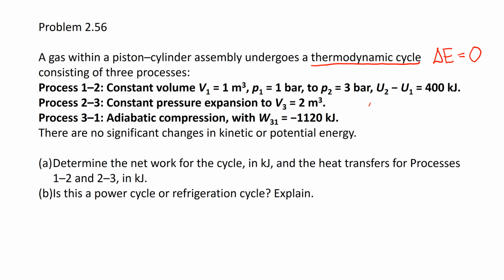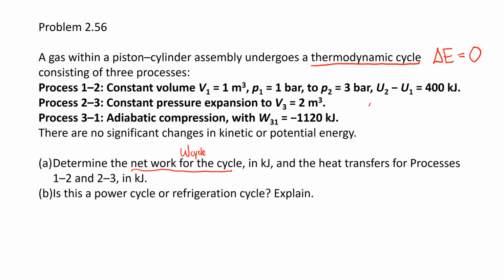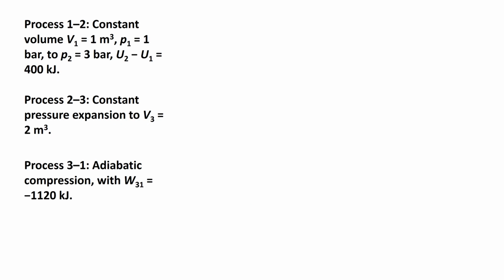And the problem is asking us to determine the net work for the cycle, so work of the cycle, and the heat transfers for processes 1 to 2 and 2 to 3. And then to analyze and determine whether it's a power cycle or a refrigeration cycle. So first let's sketch out this process.